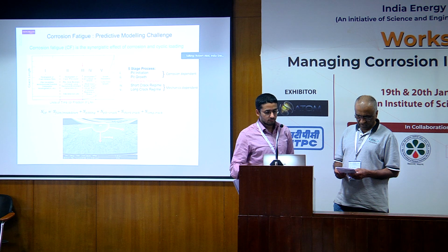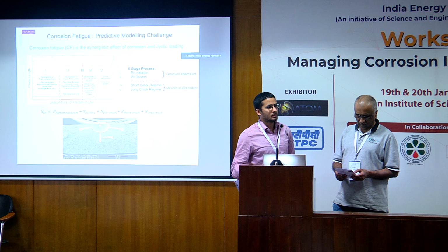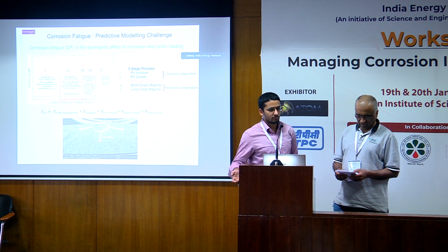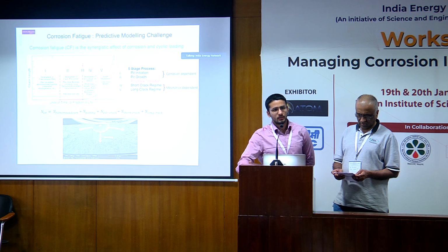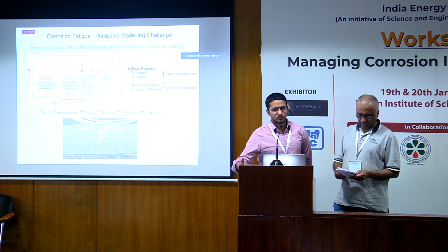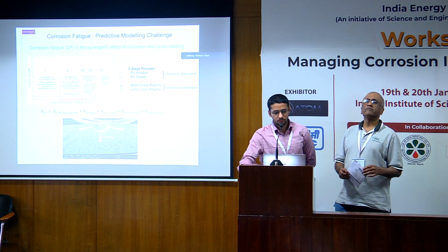At the end of this presentation, you mentioned that we should be wary of using the fracture toughness which is based on measurements away from the crack tip. Sir, can you explain why we should not use those approaches? Because we use ASME Section 11, which provides a method to analyze those defects and demonstrate how much remaining life there is.